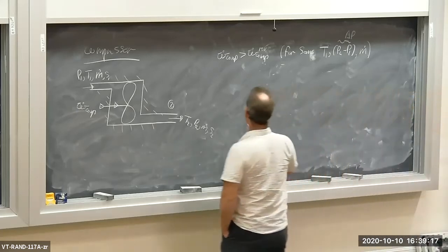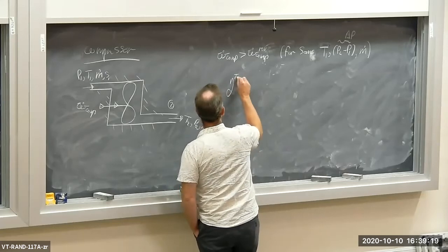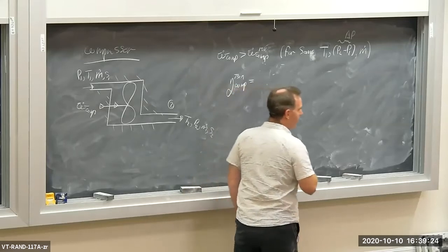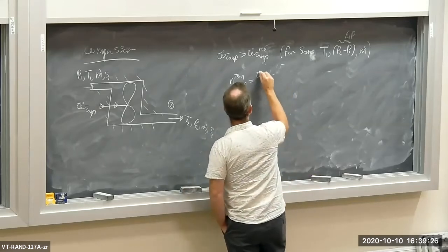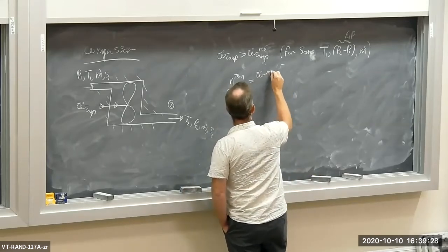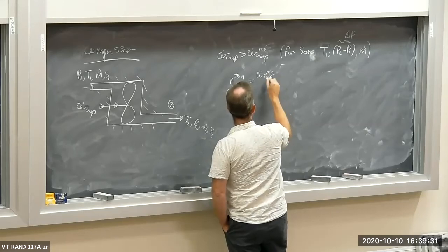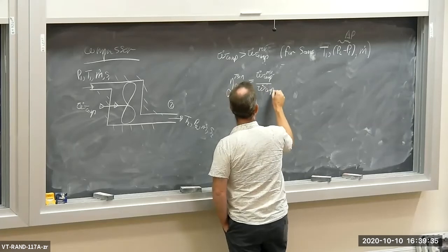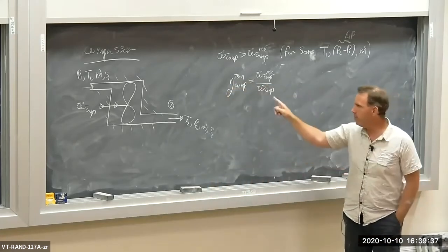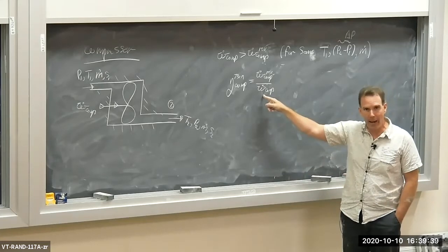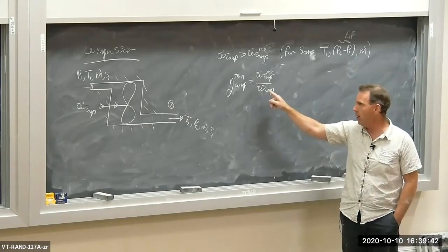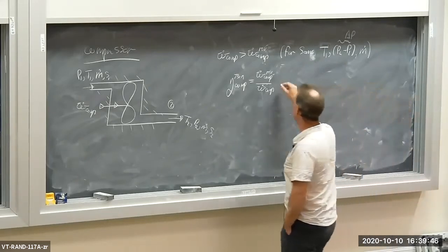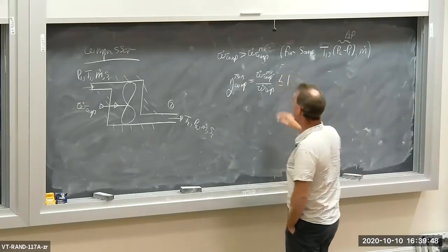So we're going to define the isentropic efficiency for a compressor as the compressor power for the reversible device divided by the compressor power for the actual device. The actual device consumes more power to pressurize the flow. Therefore, the denominator is greater than the numerator. So this is always less than or equal to 1.